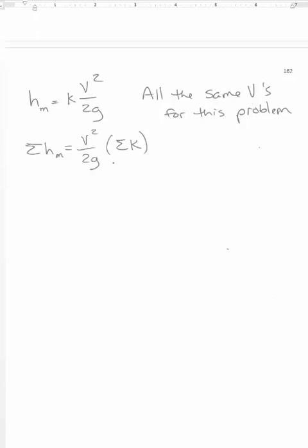And sometimes you have options, like those elbows are going to give you options, or the valve. Which one do I want to pick from? Well, if you're trying to be super conservative, you probably want to pick the bigger K values. I'm not going to try to be super conservative here. I'm going to pick some of the newer K values from the graphs instead.